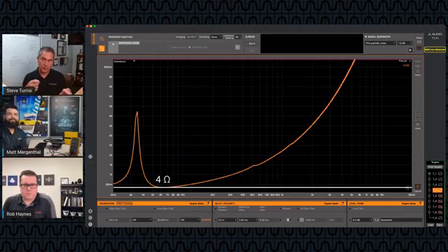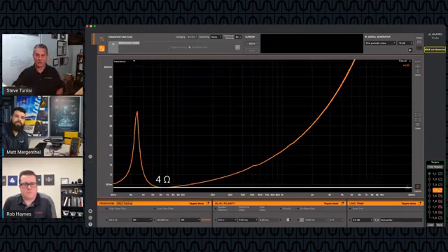You'll also see on the spec sheet for drivers like this that there's going to be a DC resistance or an equivalent resistance. And that's simply for point of reference. So when Matt took his Fluke meter and connected it to the speaker, it was reading effectively as close to a DC resistance as it could for a speaker like that. Now, there are some other things affecting it, but for the most part, you're just measuring the coil of wire. And the reason that it jumped around as it did is, as you may or may not know,